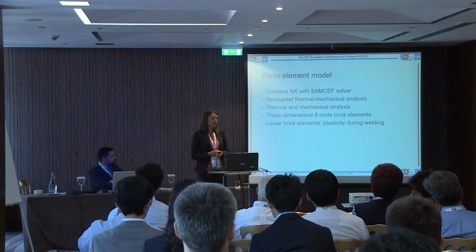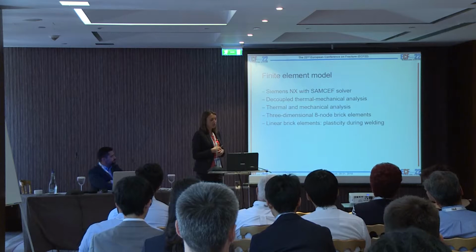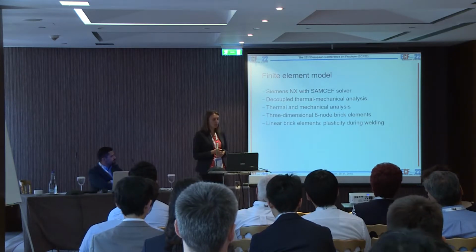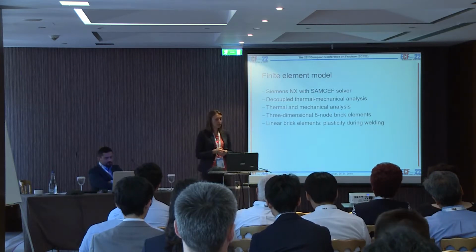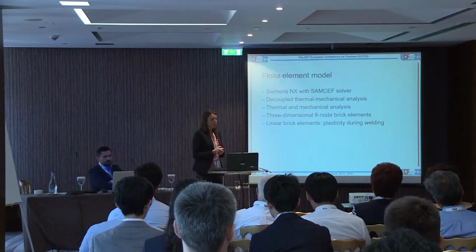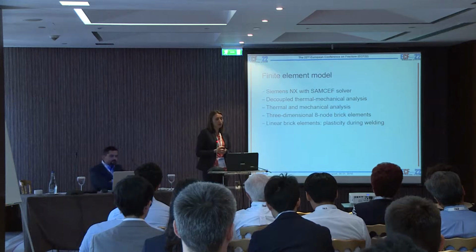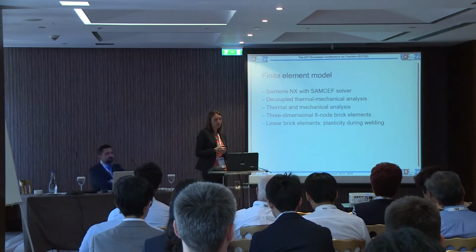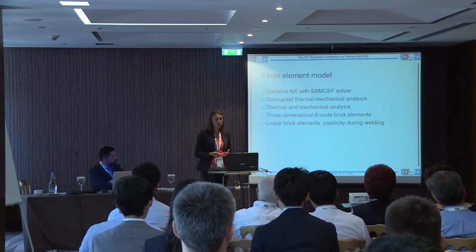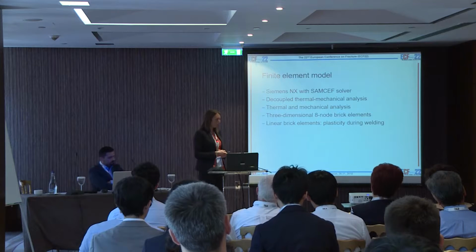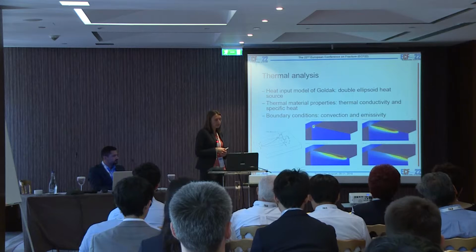For the thermal analysis, we put a heat flux on the model, and we calculate the time-dependent temperatures, and these are used during the mechanical analysis to calculate residual stresses. We made use of three-dimensional 8-node brick elements. These are linear brick elements since they are the best option for plasticity, and due to the high temperatures from the welding, plasticity will occur. So this is an image of the thermal analysis.